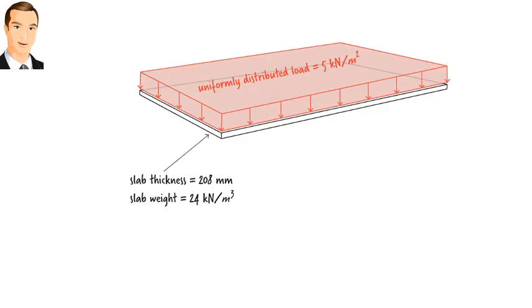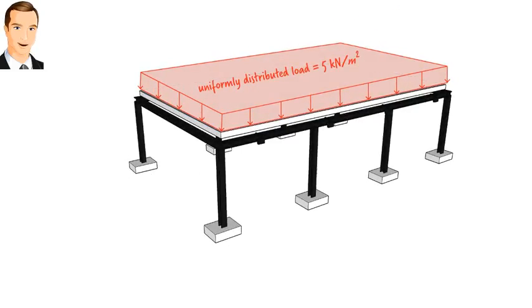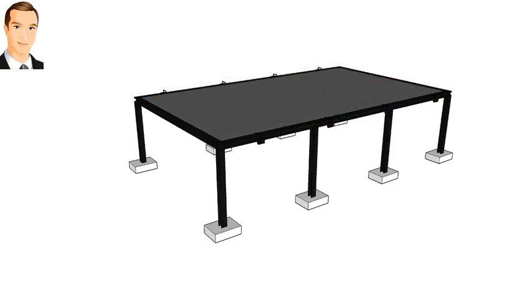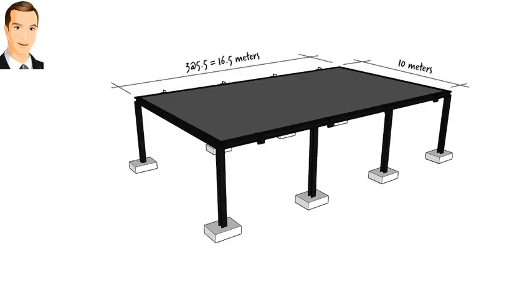Since the roof rests on 4 beams, its weight is distributed among the beams. We can determine the tributary area for each beam according to the yield line theory. This is the correct approach for load distribution when we are dealing with two-way slabs where the ratio of longer span to shorter span is less than 2. Here, the ratio is 1.65.